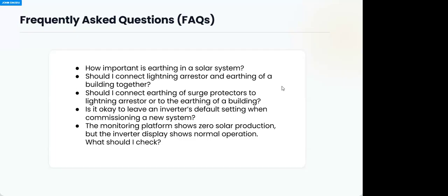For the circuit breaker, your circuit breaker can be at the input first before the stabilizer, or you put the circuit breaker at the output of the stabilizer, so that when the stabilizer has done its own regulation, it goes into the breaker. When you turn on the breaker, it goes out to the AVS, which is the automatic voltage switcher. Then after the automatic voltage switcher, you now have your surge protector. That is the sequence of a standard installation.